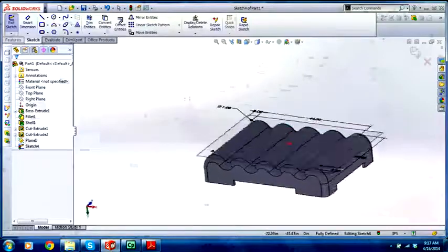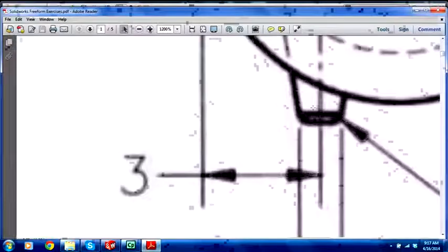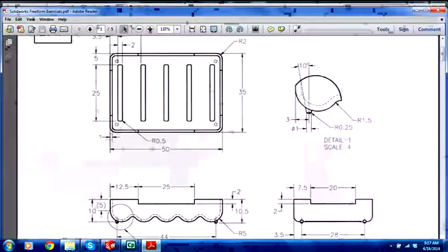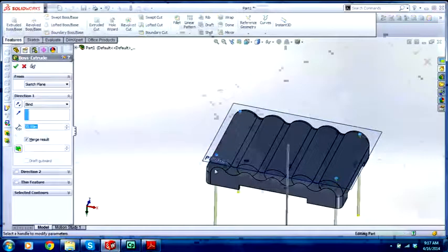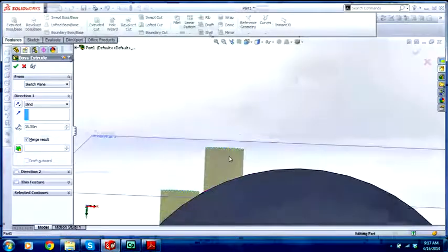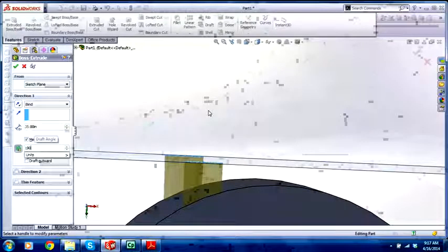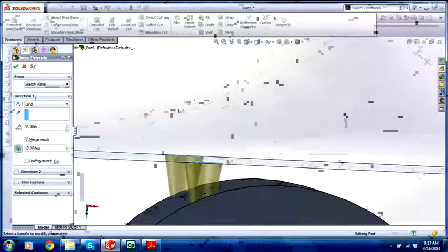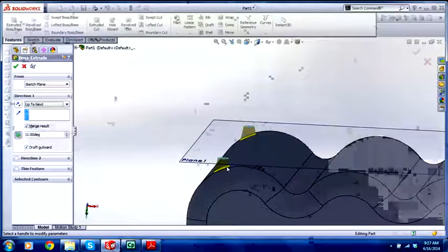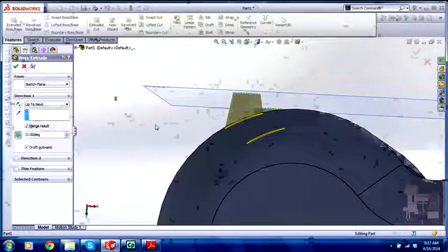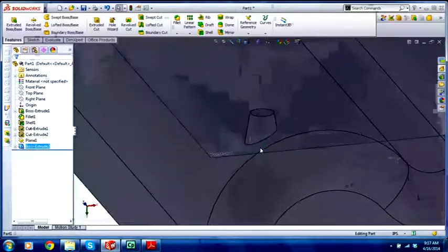Now what we're going to do now is, this starts off small and it gets wider. It has a tapered extrude of 10 degrees. So I'll exit the sketch, I'll extrude, alright, a draft 10 degrees, okay, wrong way, draft outwards, and what we're going to do is we're going to go up to next. So what it does is it just keeps driving until it reaches that face. And now we have these lovely little feet on our soap tray.